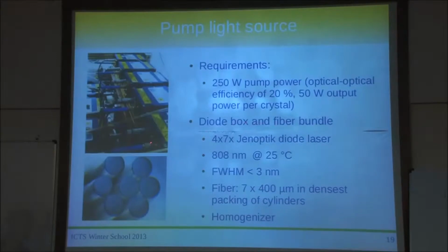So they are sitting in a diode box, as you can see here, in 2 rows. They are hooked up to a heat sink. So this copper thing here is the heat sink. There's a Peltier element between the actual diode housing and that heat sink. And then the fibers are coming out of this diode. So this is just for control, and then the power connectors are on the back of that thing.